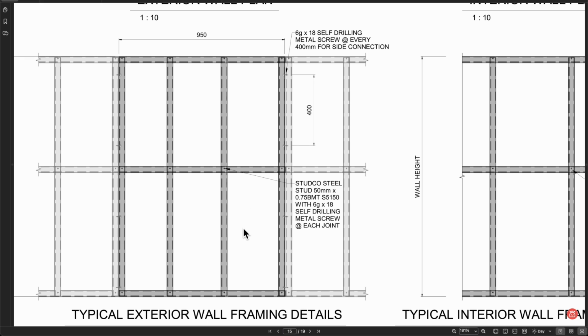And while we're on that topic, this is the other thing I was talking about, the sheeting going on horizontally. That face there is not a wide enough face, and building codes won't let you attach your sheeting joins to that smallest face. So that's why I've got to put them this way, because now they're 36 wide on the sides of my studs. So that's why I did that.